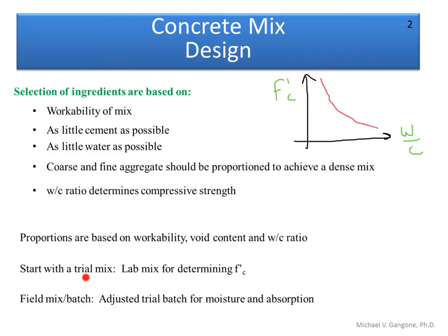And as we do a mix design, we have to keep in mind that we're starting out with kind of a trial mix, so to say. This is kind of the first round or first batch that we put together. And this first mix is, so to say, based on, or does not include, I should say, or account for two main things. Number one, any surface moisture or any moisture that might be in the aggregate.